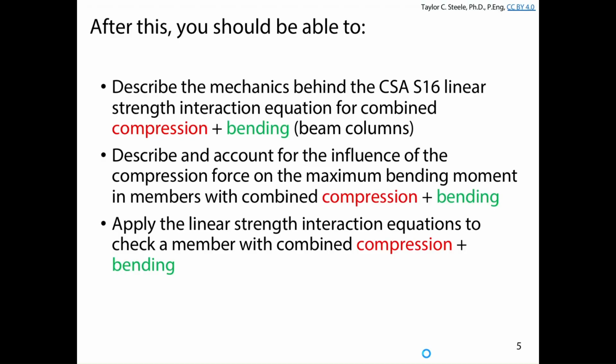The stuff we're going to talk about, this part here, where we introduce U1x and U1y, applies to all beam columns. But the last objective here applies primarily to class 3 beam columns, where we want to keep the maximum compressive stress less than yield, because local buckling is going to get in the way. Next day we'll talk about nonlinear interaction for class 1 and 2 beam columns.